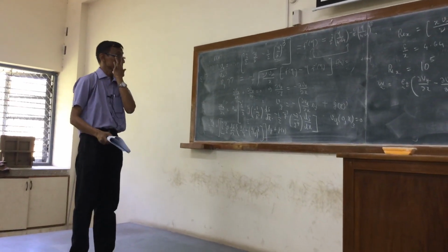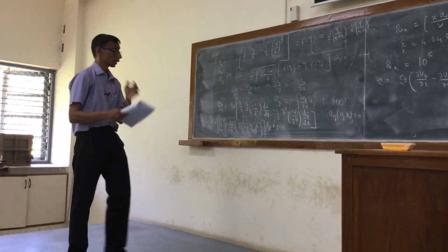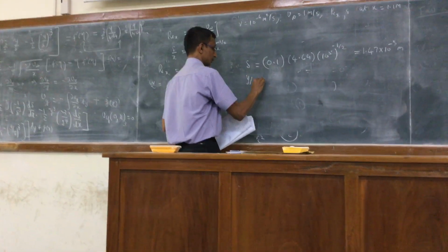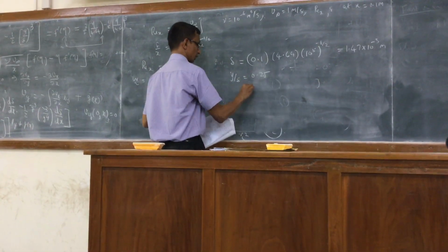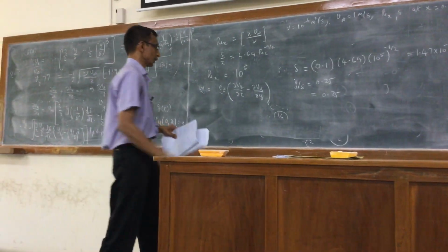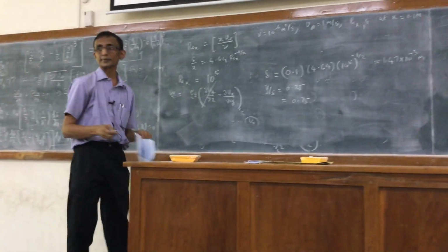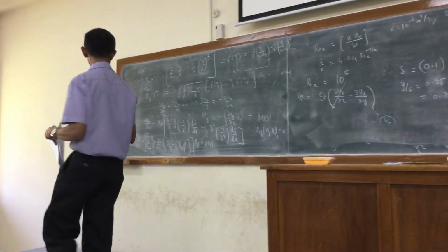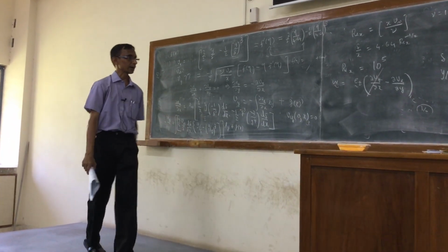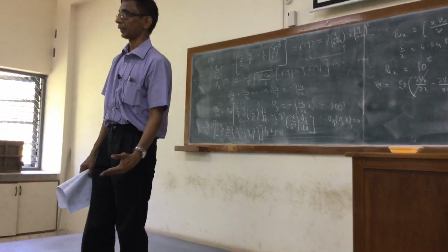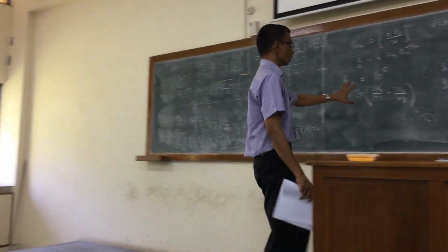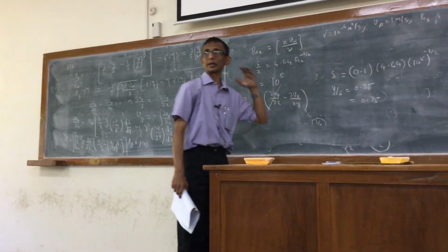So clearly, when you are asked to calculate it at y over delta equal to 0.25 and at 0.75, you are also asked to neglect, as a first approximation, this term. You can also calculate it because we obviously have an expression for Vy, and you can calculate dVy by dx and convince yourself that it will be much smaller than dvx by dy.